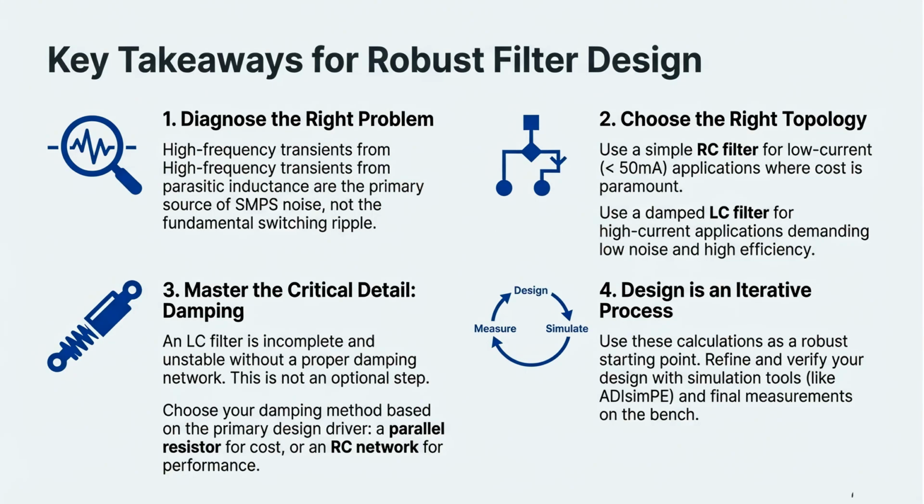To summarize, diagnose the problem as high-frequency transients. Choose the right topology, RC for low current and damped LC for high current. Mastering damping is critical for LC filters, and remember that design is an iterative process requiring simulation and measurement.